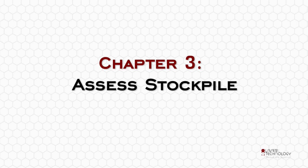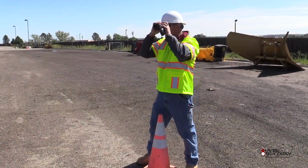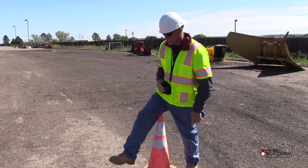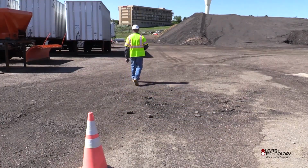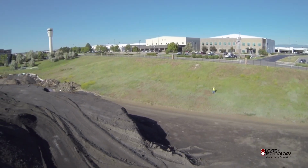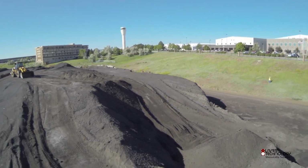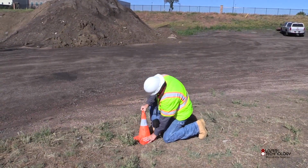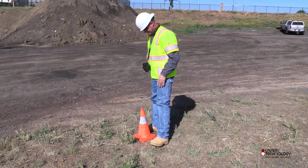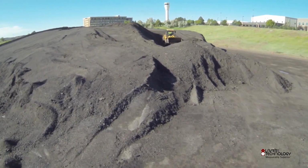Chapter 3. Assess stockpile. Walk around the pile to determine your best point of view for each control point. Be sure you can see the control point behind you and establish a good position where you can see any major irregularities of the pile. It's recommended to minimize the number of control points. If necessary, you can traverse onto the pile to measure anything you can't see from the perimeter.